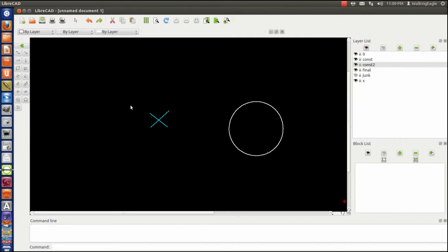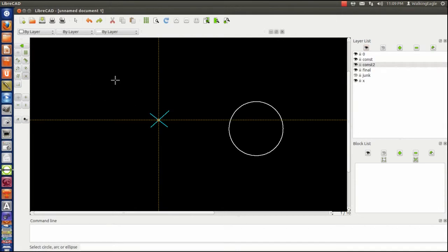This time we're going to do a tangent to a circle through a point out there somewhere outside the circle. To do that in CAD is trivial again. We'll go to the main menu, go to Line, and choose tangents from point to circle, so it's already done for us. We go to our point, which is at the X, and now we go to circle or arc, and we're done. That's all there was to it.